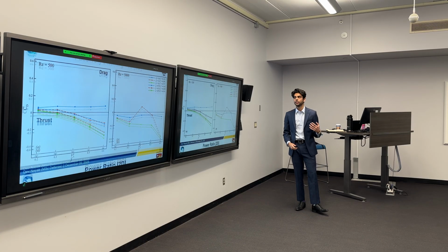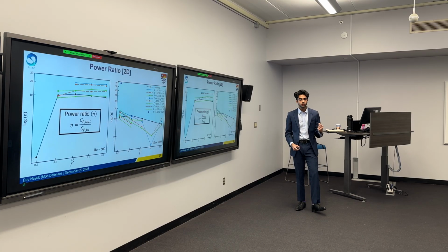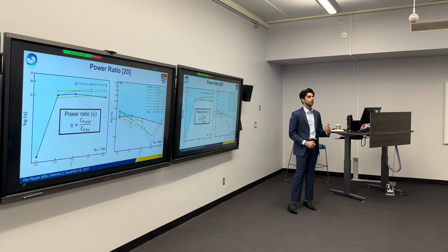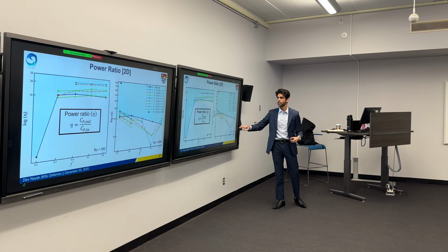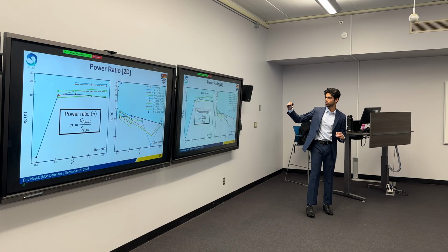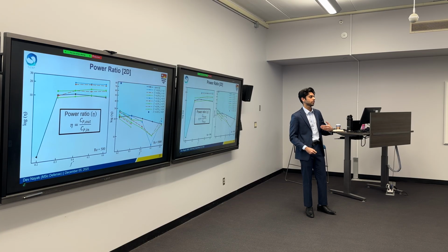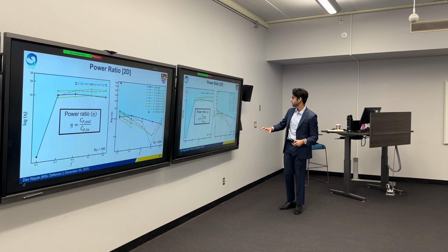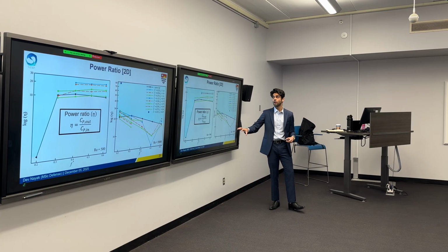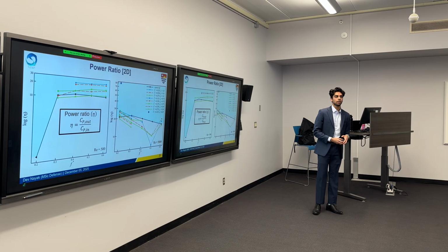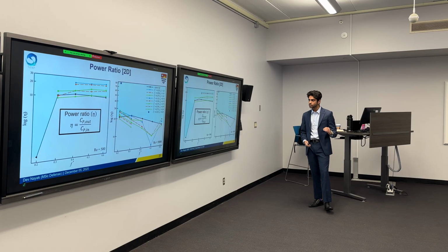Now, not only the thrust is important, but for the two-dimensional analysis, we have incorporated a power ratio that shows how actually our swimmers perform. Here, we can see the dark line shows the trend of the actively pitching tail, and anything that falls above this trend shows better performance in terms of their swimming capabilities. Another aspect we can grasp from this is that for Reynolds number 500, there are a lot of other cases that can produce better performance compared to Reynolds number 5000.